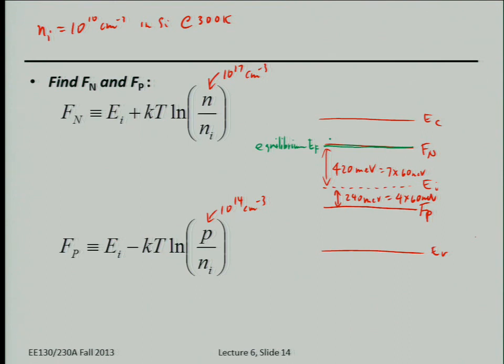But now this is not in thermal equilibrium because the concentration of electrons and holes is not only dictated by thermal generation and recombination. It's something external, either applying an electric field to inject carriers or shining light to add more electrons and holes. Does that make sense? So equilibrium actually always implies thermal equilibrium. You can think of it as the natural heat, vibrational energy, that generates electrons and holes in your semiconductor.